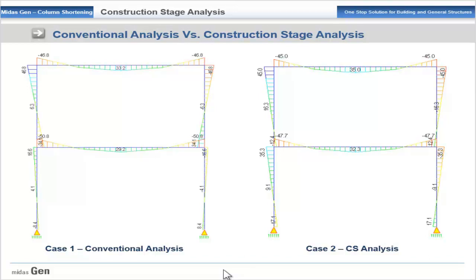Thus, with the shortening of the structure, moments increase ultimately. These moments, if within limit, can be compensated with more reinforcement. This is usually considered in short structures. But for high-rise structures, the moments would go higher, and thus a necessity of performing column shortening analysis arises. The compensations are then in the form of increasing the heights of vertical elements.